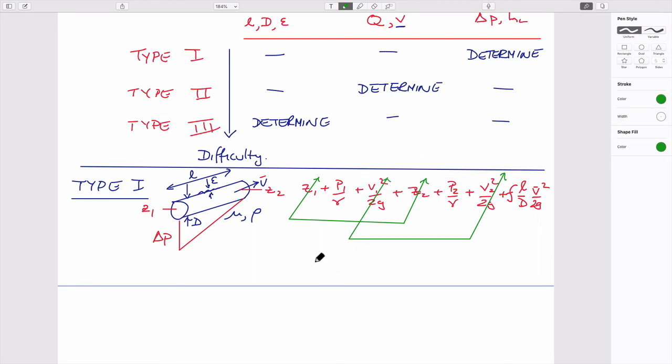And we'd be left that delta P1 minus P2 over unit weight is equal to friction factor, length over diameter, V squared over 2g. And that's just by definition exactly the same as head loss in our system. In other words, upstream pressure is larger than the downstream pressure. That loss in pressure is basically dissipated by the force that's applied to the pipe by the flowing water. So you physically have to hold the pipe against that drag, internal drag of the fluid.